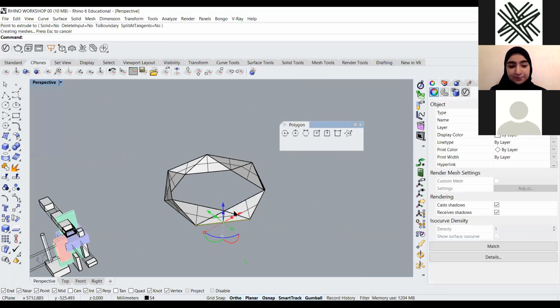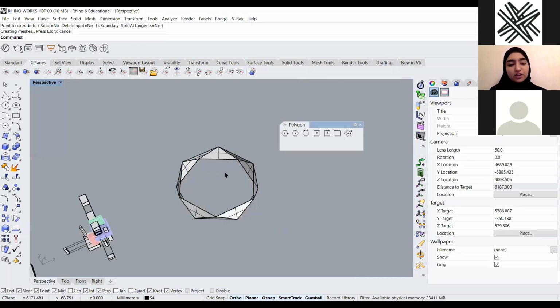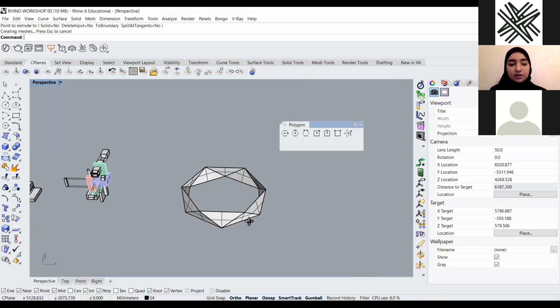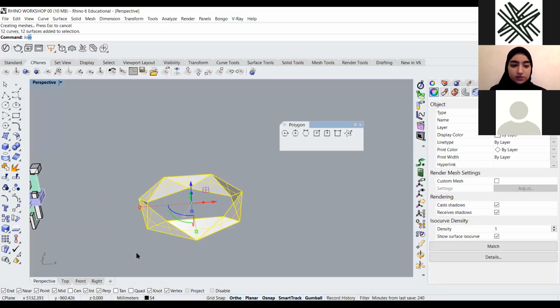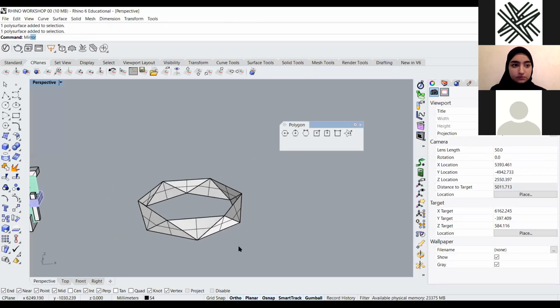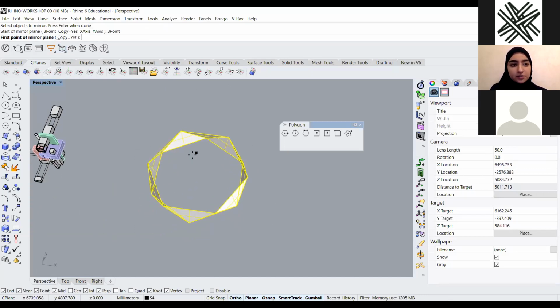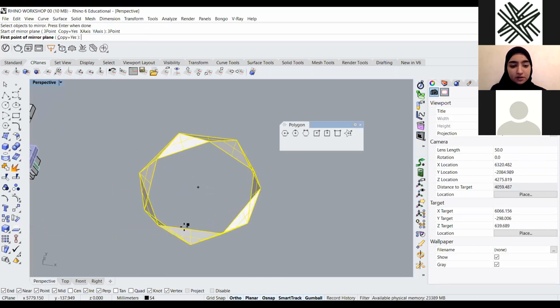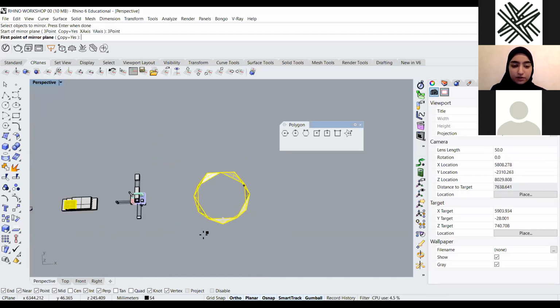So now I'm done with that shape. Now I have to mirror that shape and then just copy. So first I'm gonna join the surfaces. Okay, then mirror. Object to mirror, this one, enter. And then there's an option called 3 points. I'm gonna click on 3 points, and then first point of mirror. You can select honestly everywhere. I'm gonna select only the middle of the object.